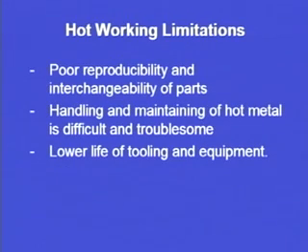Other limitations of hot working are poor reproducibility and interchangeability of parts. Handling and maintaining hot metal is difficult and troublesome, and there is lower life of tooling and equipment. This may be because of thermal shock or some other reasons, but the life of the tooling is comparatively less in hot working operations.